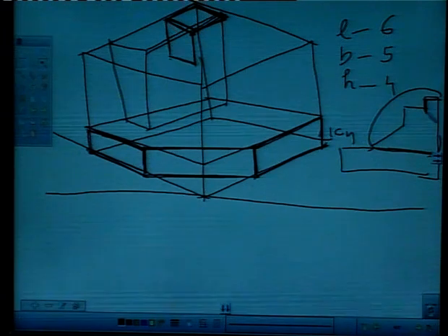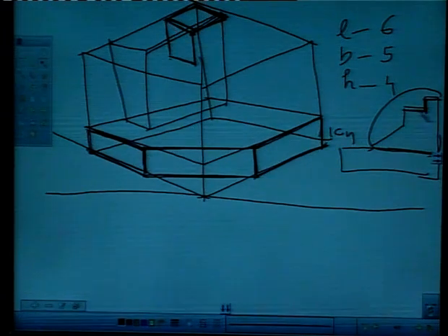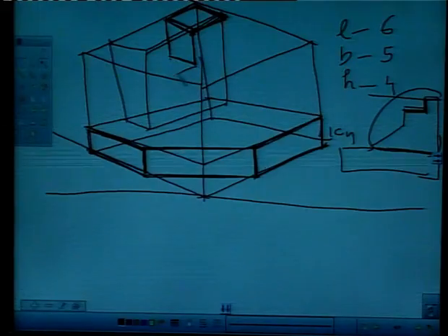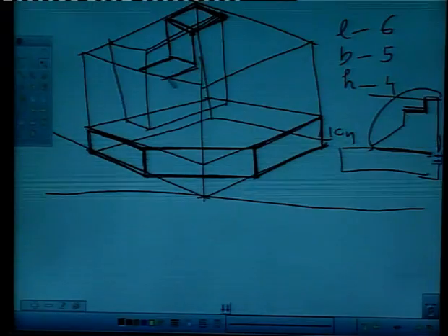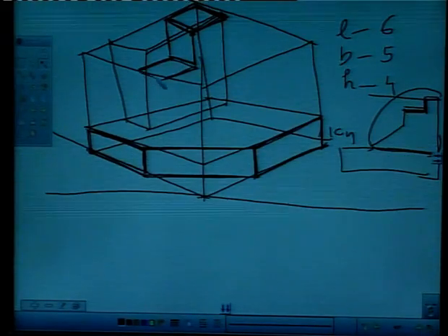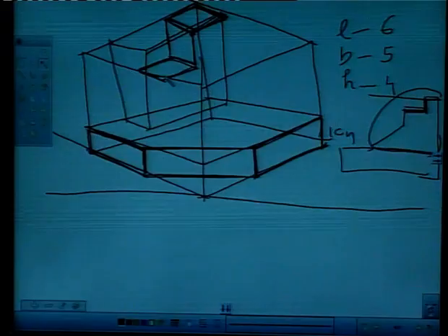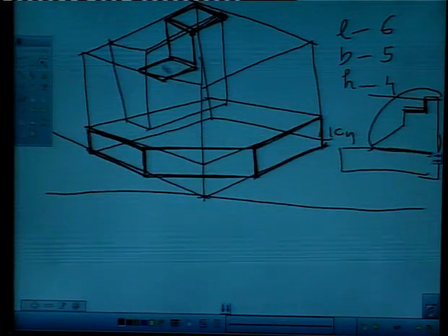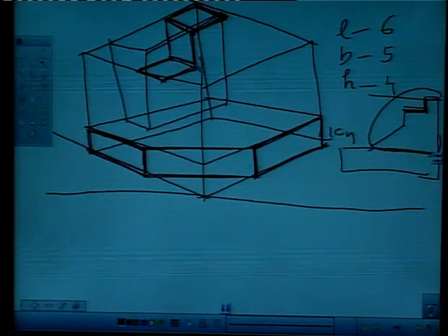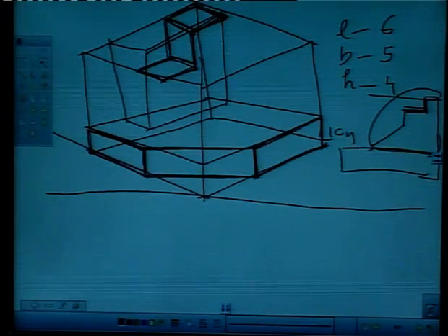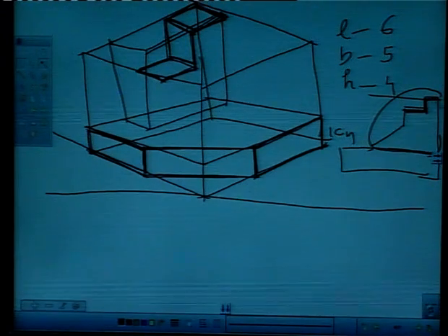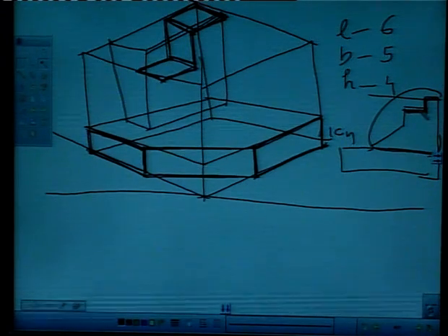Right? Then there is a horizontal line again, this. So, this line will be parallel to this line. So, we have drawn at 30 degrees like this. Right? And this is again 1 centimeter as per our drawing's dimension. Right? We have started working from this corner. First of all, we worked this surface, then this surface. Right?